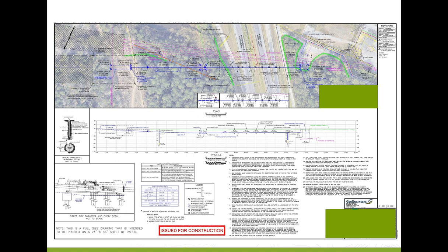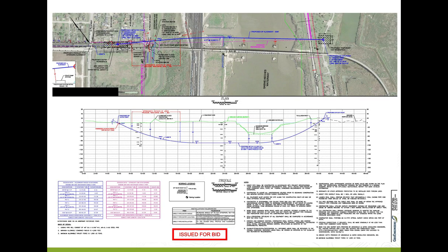So this would again fall into the category of minimum length, minimum depth sort of HDD. This crossing was designed more on an HDD-like profile. In fact, it was initially proposed as an HDD, but we could not get the factors of safety for hydraulic fracture to work out for it.